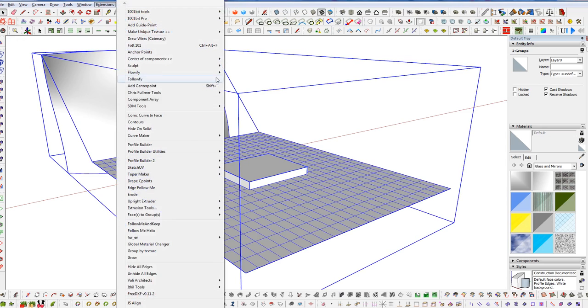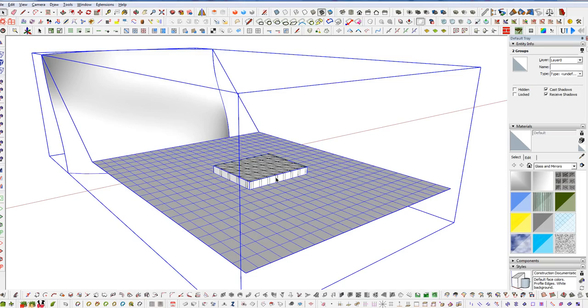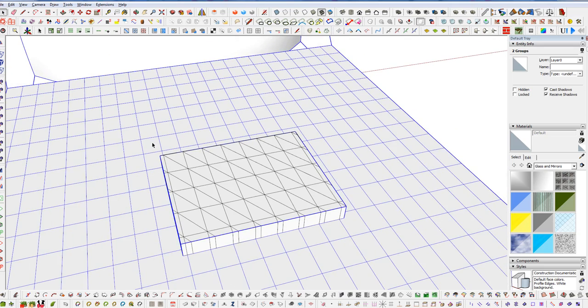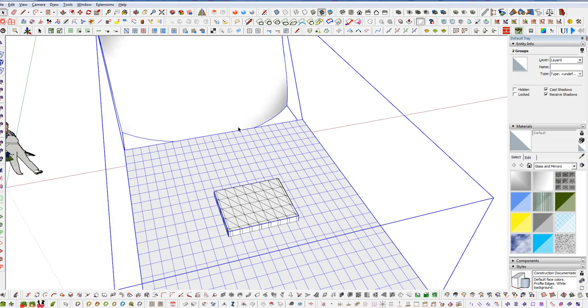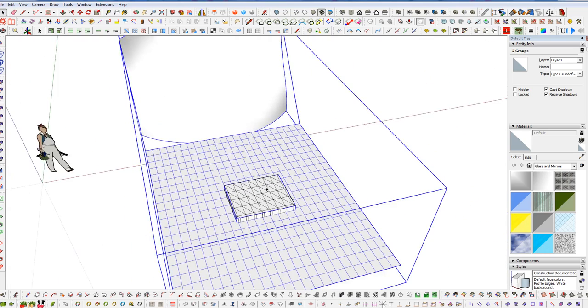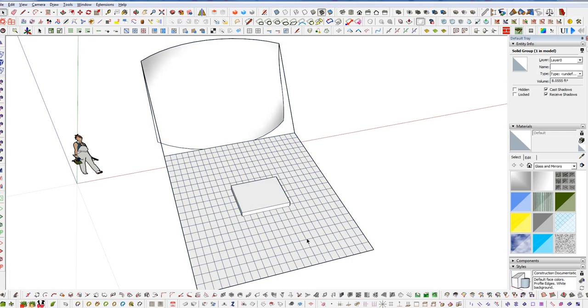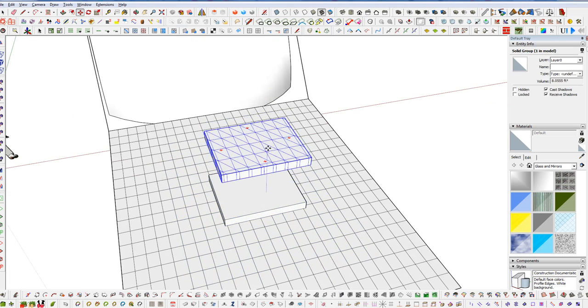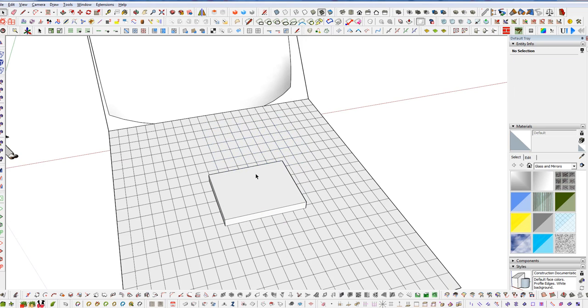We can also get in here, and if we would go Flowify cut, it's going to divide up this geometry based on what's at the reference image, and it's going to actually cut in those quad edges there along the sides as well. And you can see it puts that in its own group separate from the mesh here, or the geometry, and doesn't replace that.